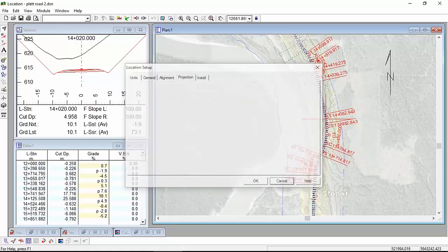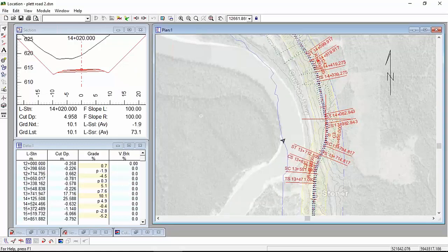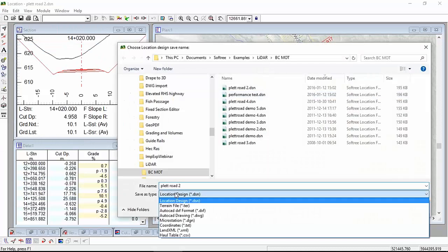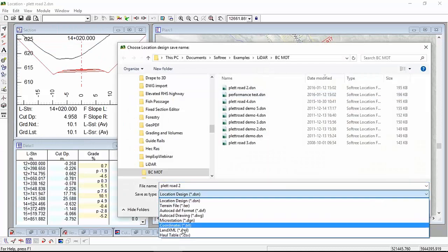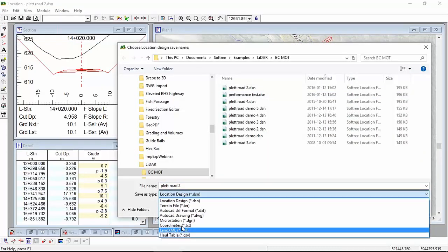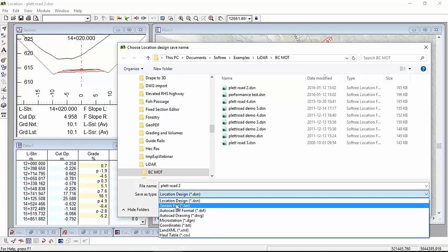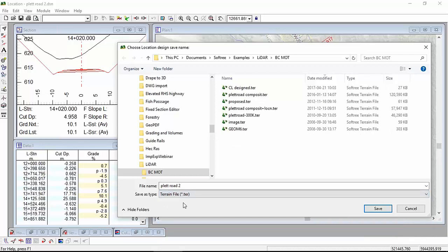Okay, so I got a well-defined coordinate system. I can extract lat long from this. So let's save as, oh, Google Earth isn't in here. Neither is shape. Both of those things are a nice way to get georeferenced information out and display it to somebody else. How can I do this? Well, it turns out the way you do that is you export to terrain.